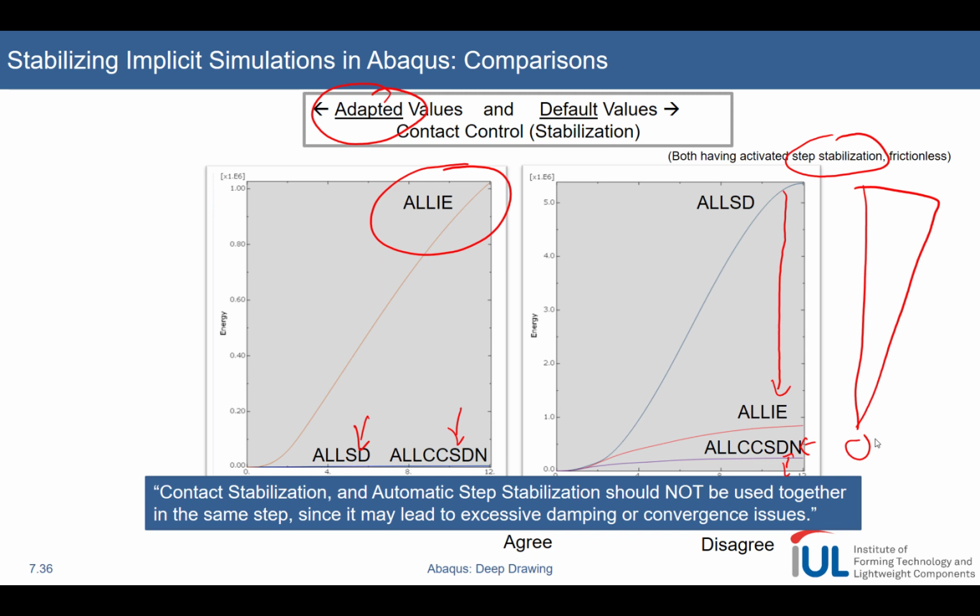However, and this is what you've seen on the left here, if these terms are negligibly small and still do their job, meaning that using them you actually reach convergence and you don't face any other numerical issues anymore, then the computational time to obtain the results is vastly less than if you'd chosen dynamic explicit simulation. That would have been the alternative, and we will also later talk about this.